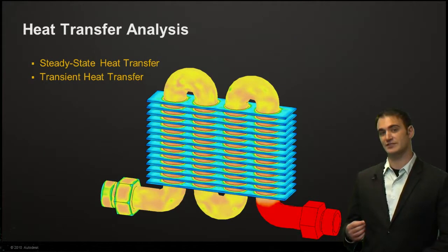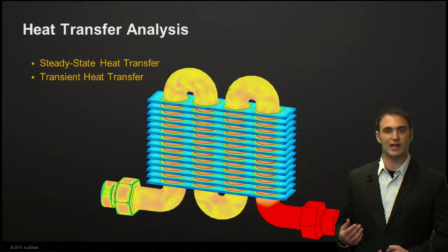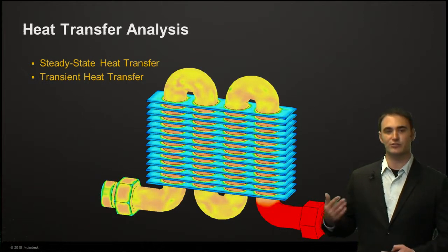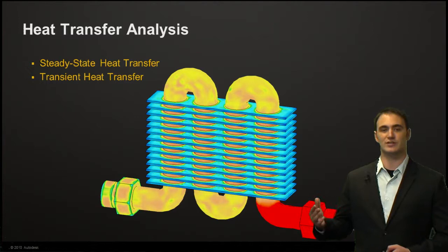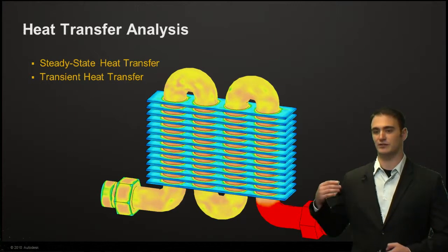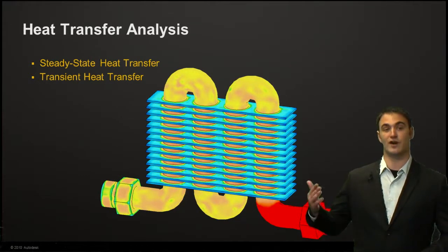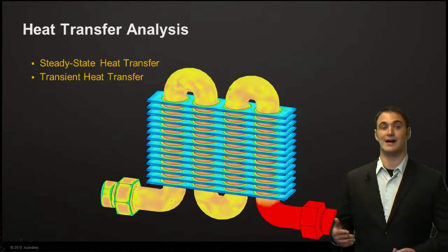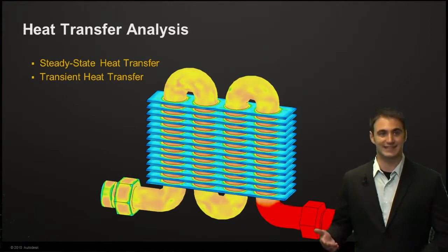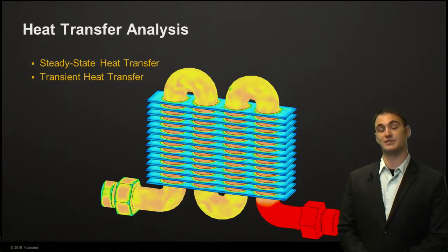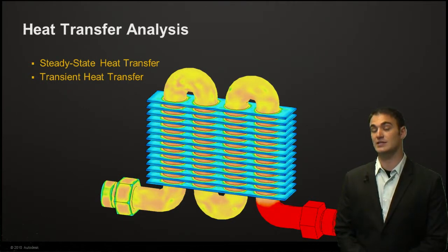Now, heat transfer analysis, in my opinion, is pretty straightforward. This is conduction, convection, radiation. You put in input loads such as temperatures, a particular convection, a heat flux, things like that. And the outputs are going to be temperatures. You can look at temperature profiles, temperatures through parts. You can look at the rate of heat transfer through any given interface, things like that, right? And this is both steady state and transient. So you can look at time dependent loads, or time varying temperatures as well.